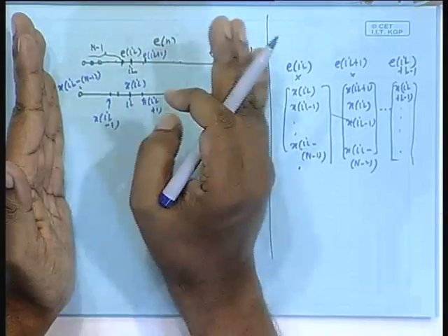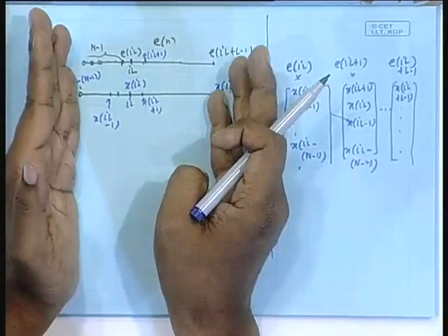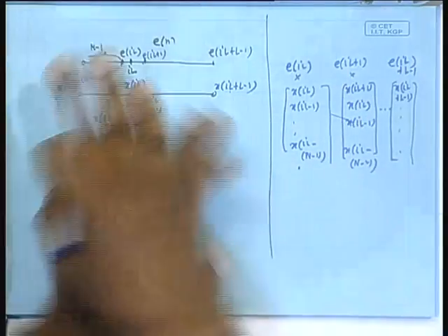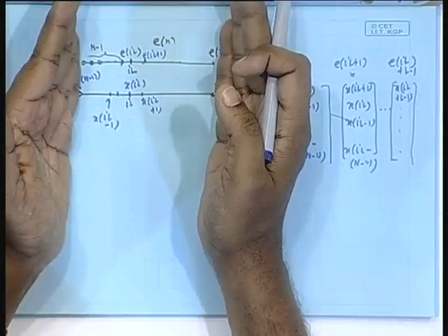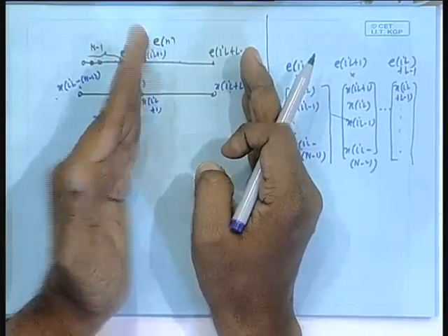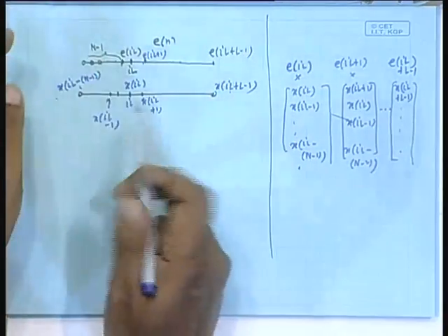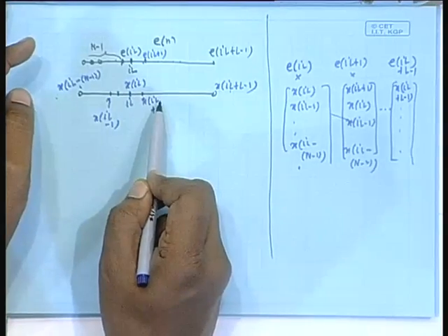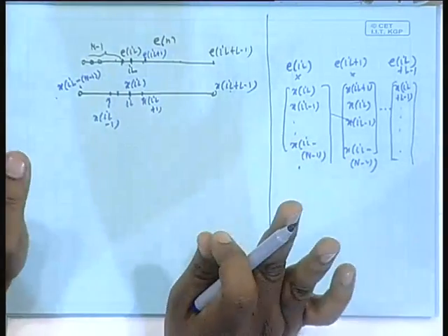If you proceed for circular convolution, you will get this. That is, make a periodic version, reverse it, then without shift, whatever you see in the window, multiply, you get the first entry, then shift it once. In circular convolution, you go on shifting even beyond the n minus 1 shifts, because you have to complete the entire thing, but I will ignore those results, I do not need them.